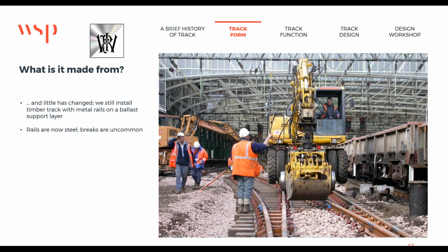We still use the three main components which made up the early track forms: crushed rock, wooden sleepers, metal rails, and it can be said that the present day track has developed little since the original construction concept. Of course, these days we use longer, 60-foot minimum, 18288, and stronger steel rails, but these are still connected by mechanical bolted fish plate joints, and railways are often supported on wooden sleepers on ballast.